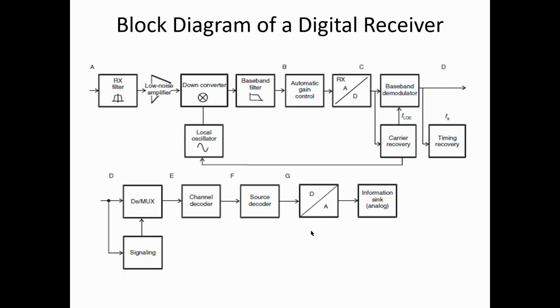The signal we receive, which travels in free space, will be analog. So we must convert the signal to digital for further processing. For that we are using an ADC here. And then the demodulator, which is the reverse process of a modulator. Here we mapped the zeros and ones into corresponding symbols; now, with respect to the corresponding symbols, we must get back the inputs of zeros and ones. For that we are using a demodulator at the end.